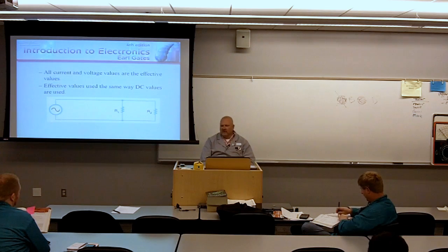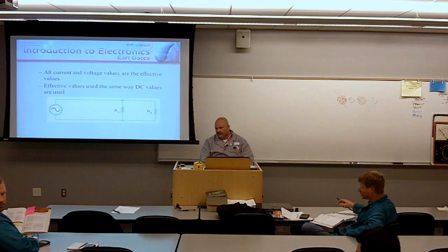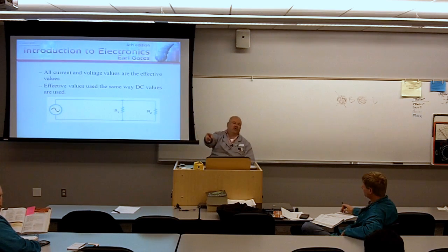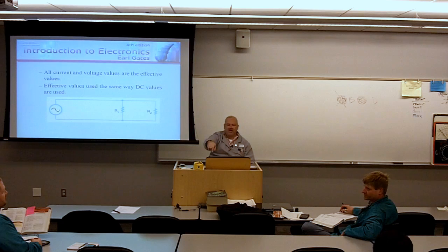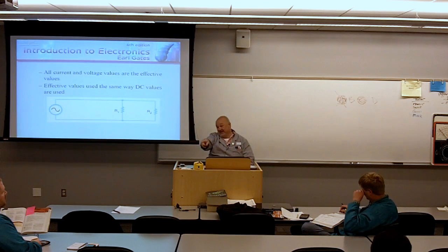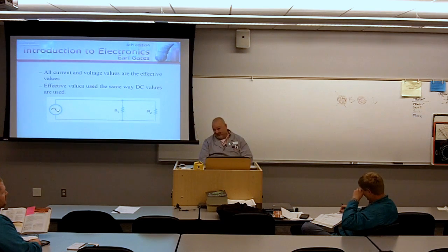What do you got there, Mr. Carter? What type of meter is that? Is that digital? So the fun thing to do would be to do a comparative analysis of that meter, one of our Fluke meters, and an oscilloscope. And then just start gradually plotting it out and seeing, and you'll probably be surprised that an analog meter might give you the best results above 1,000 hertz.